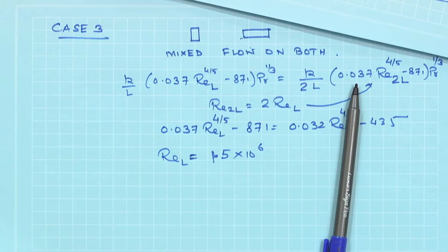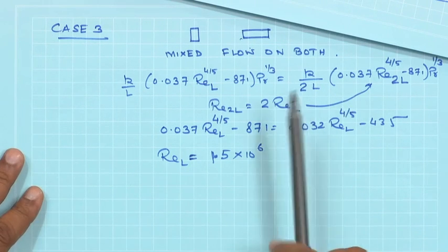And later on, when you study mass transfer, you would see that the same analogy is applicable to mass transfer processes as well, but we are not considering that at this moment. But the same Reynolds or modified Reynolds analogy is equally applicable for mass transfer. So, from the analogy we obtained the relations for turbulent flow Nusselt number and mixed flow Nusselt number. So, from the next class we will start our discussion on internal flows, flows that are taking place inside a tube, and how to handle them.